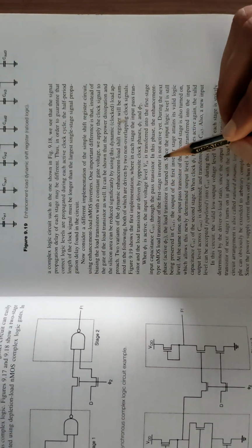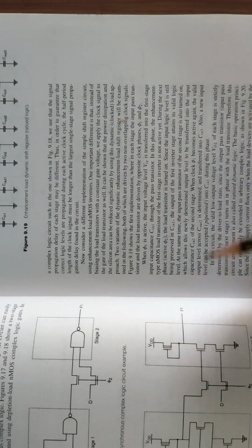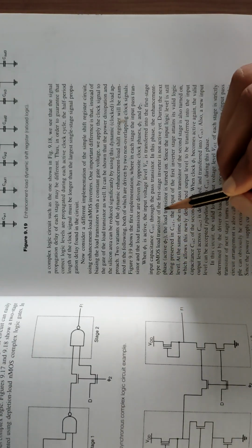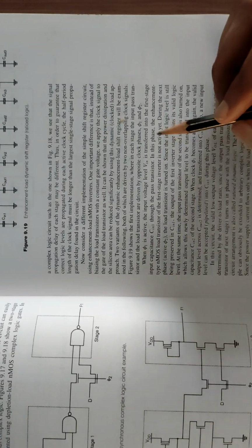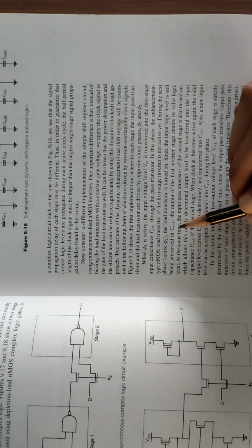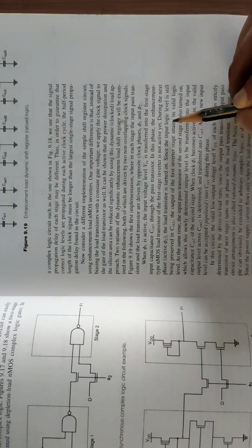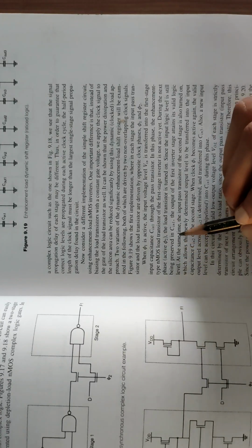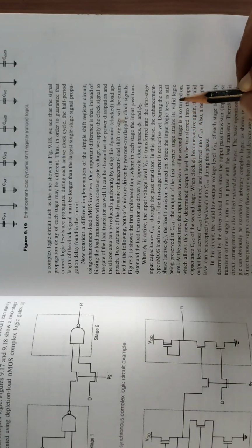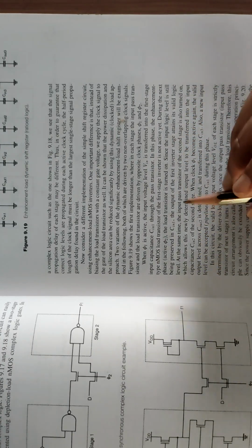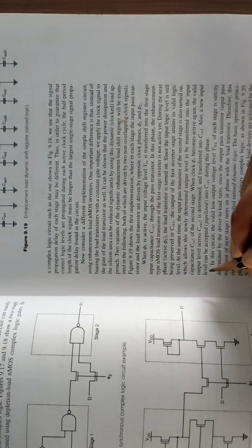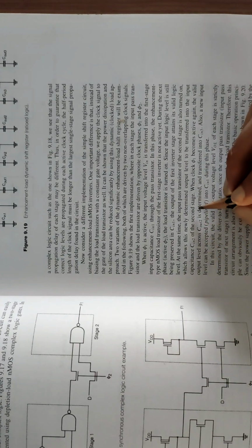In this phase, the enhancement type NMOS load transistor of the first stage inverter is not active yet. During the next phase, active phi 2, the load transistor is turned on since the input logic level is still being preserved in Cin1. The output of the first inverter stage attains its valid logic level, which allows this newly determined output level to be transferred into the input capacitance Cin2 of the second stage.